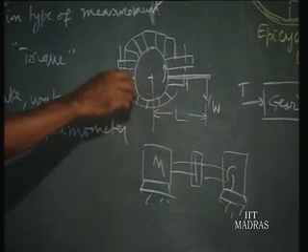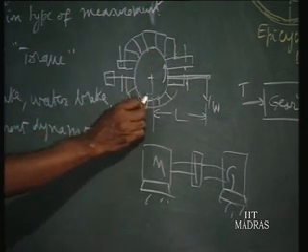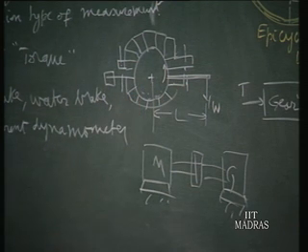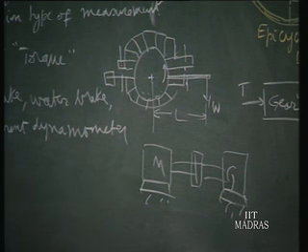So when you absorb energy, this whole thing is heated, and to cool it, normally in the drum we pour some water in during experiments in IC engines. This is one of the experiments at the undergraduate level. Otherwise we may have a water brake, where the viscosity of water is made use of, and that is the second torque measurement, using a water brake.